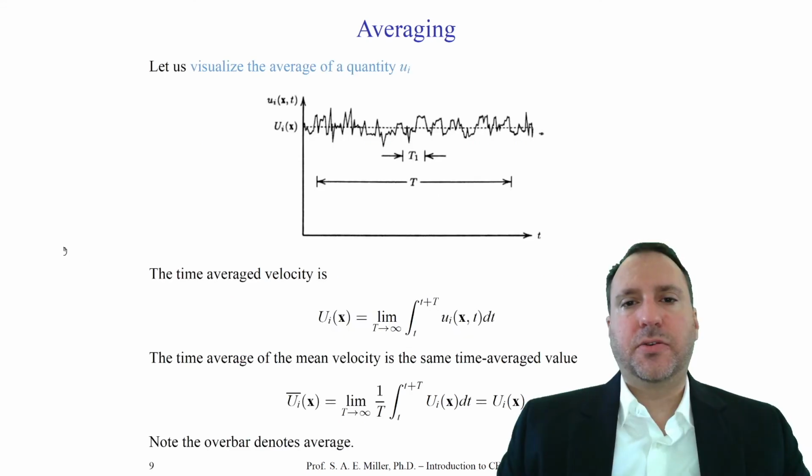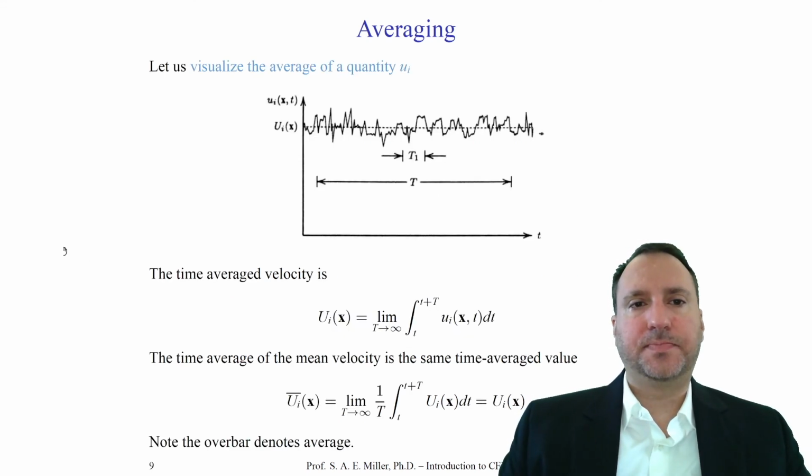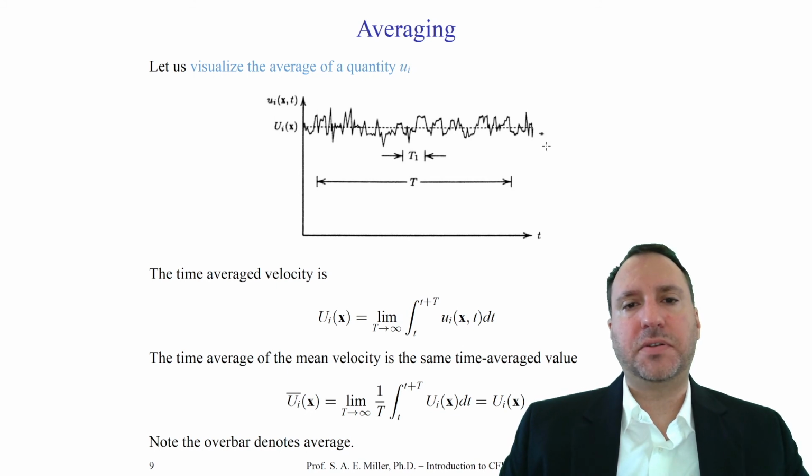Let's visualize this so this choice makes physical sense. In this particular graph, we have an x-axis, which is time, so time is increasing. On the y-axis, we have u. u is the original velocity variable in the Navier-Stokes equations, as an example. Now, u is illustrated in this graph as the solid line. That's the original value of u, and what we would ideally love to predict. Instead, we'll try to predict the average quantities and the statistical quantities derived from u prime and u.